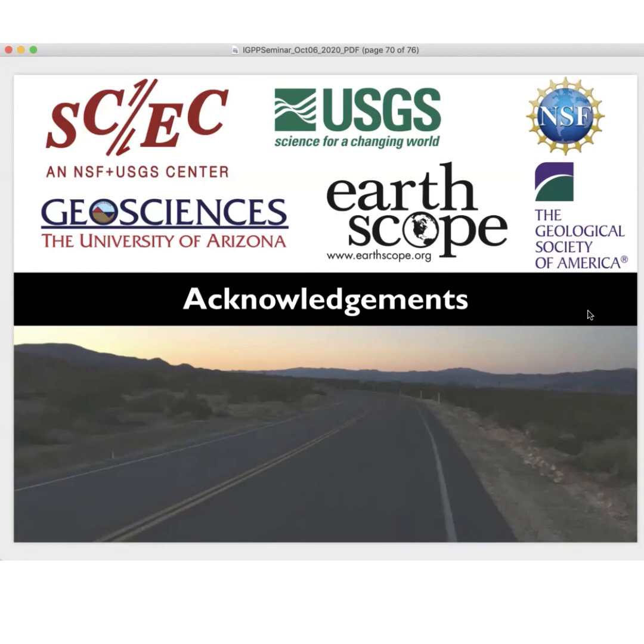And for the Coachella Valley dip, we have it dipping slightly, but we actually had some reviewer feedback in our paper on whether it should be dipping all the way to the surface or not. So we did a test case to see how much that dip would affect the final parallel slip rate we got out of that, and it didn't end up affecting it too much. But for the actual fault geometries we define, we take that information from the SCEC community fault model and the USURF fault model. And I think for Coachella, we have a partial dip of 60, and in San Gorgonio Pass, we get down to 25 degrees dip. So those are sort of the low end estimates.